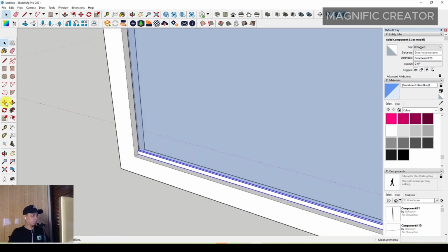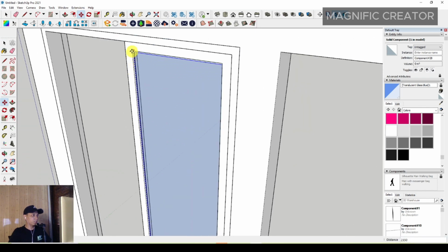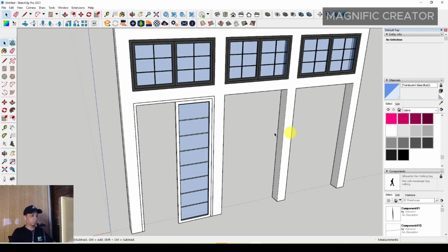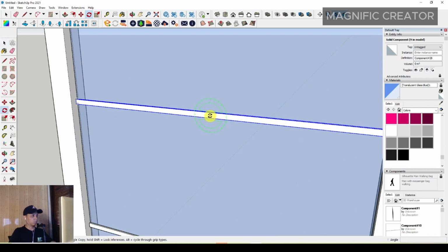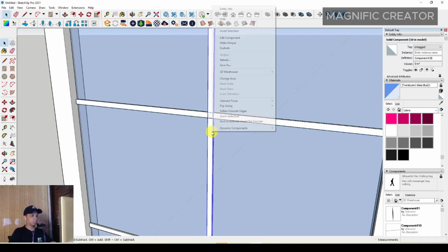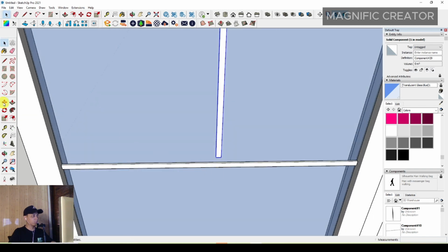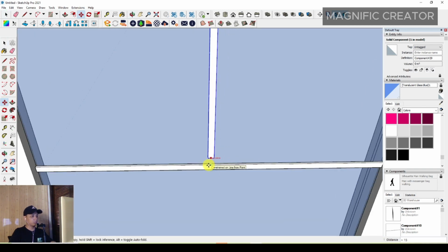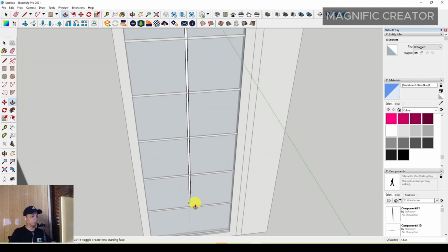And after that you have to move and press control until it is on the top position of the door leaf anyway. Then you can type maybe 8/enter, so it will divide automatically. Then you have to rotate it and press control, so it will be duplicated, and then you type 90 degree, and then right click and make it unique to make a vertical divider, and then position it on the center position of the door leaf. Then you have to push with the push tool until the bottom position.